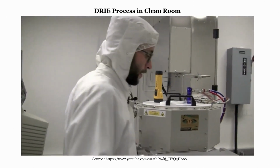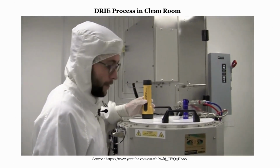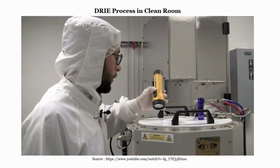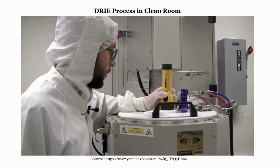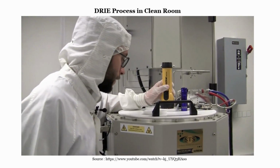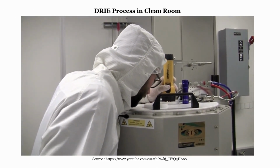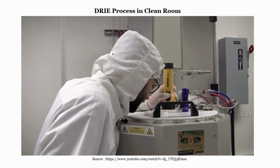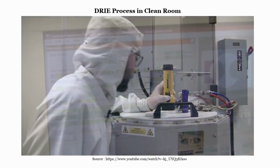Once the wafer is loaded into the chamber, we have a flashlight here in the machine to check that the wafer has been loaded properly, so we have to turn on the light and check through the window that the wafer is placed properly and the clamps inside the machine are holding it in place.